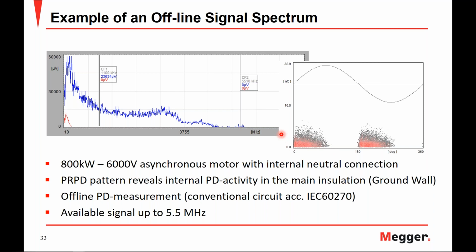And just to give some background of what a phase resolved partial discharge pattern is, this is actually a 3D graph that provides the phase angle, the magnitude of discharge, and the color is the repetition rate of the discharge taking place, where gray is fewer repetitions and red is more. And we'll look at a couple of other phase resolved partial discharge patterns a little bit later.